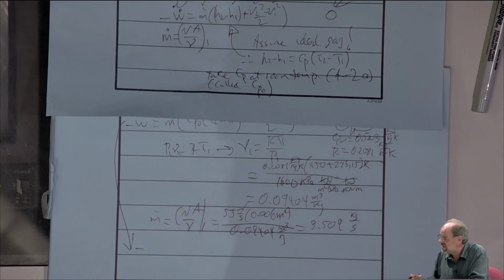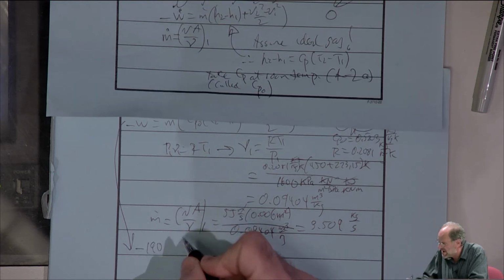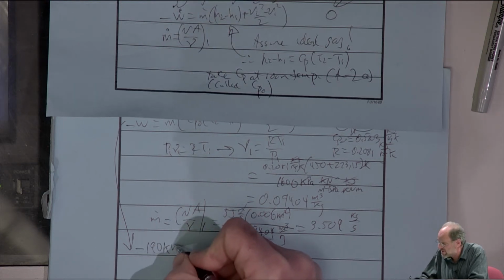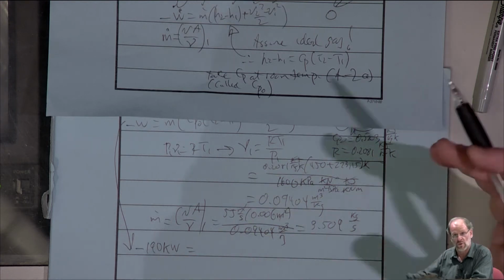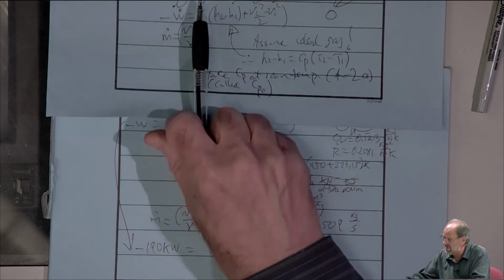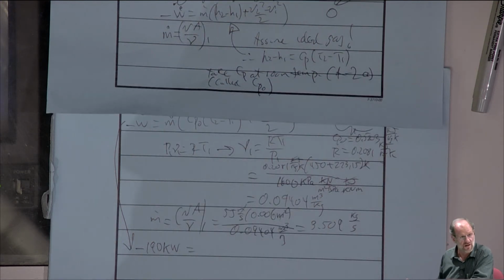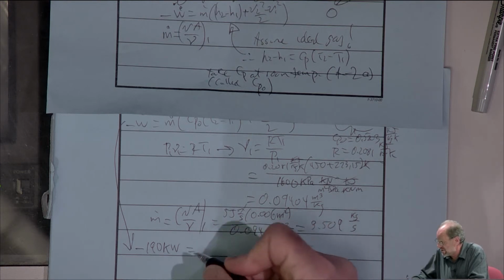So we have the negative of power. Again, I want to remind you, don't confuse the sign within the equation with the sign of the work term. Same thing applies to the heat transfer term, right? Work is being produced by the system. It's worked out, it is a positive number, but there's that minus sign as part of the first law. So don't get rid of the minus sign because you know there's a positive work term. Leave the equation be. I mean, it's the first law. You don't want to mess with that. You just want to make sure the signs are right in all the other terms. So negative of a positive number, and then just throw in all the rest of what we have.